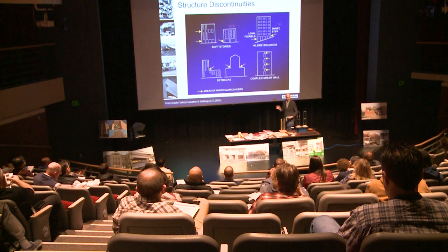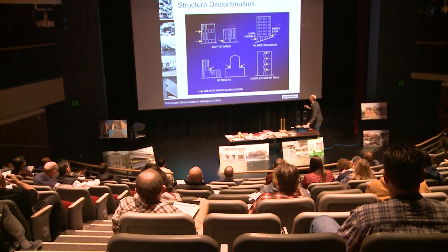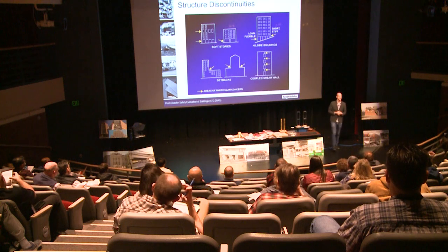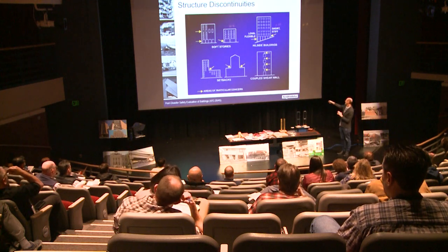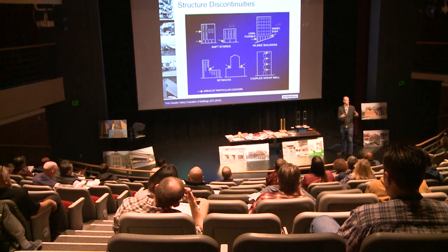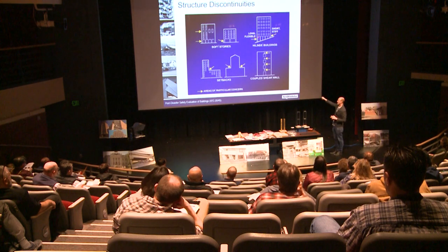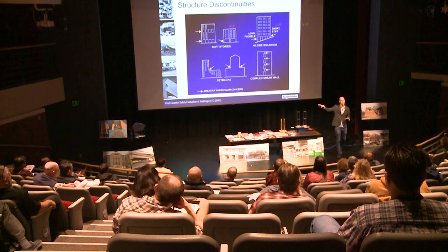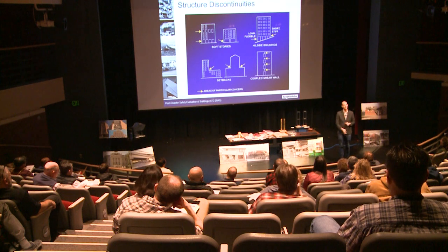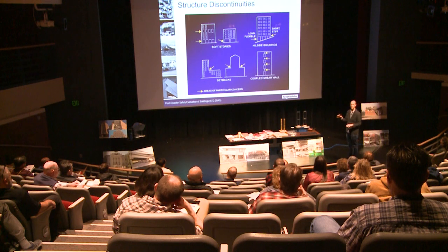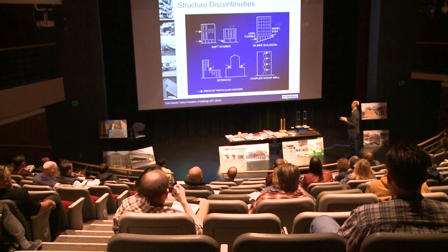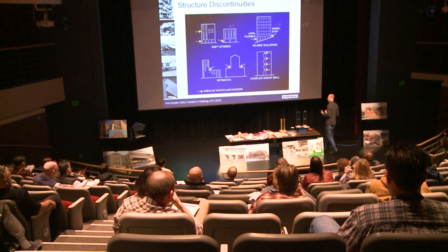Another concept that I just want to take a second to deviate and talk about for this hillside building is, let's say all the columns on this building are equal, the same columns. So they're the equal cross-section, same reinforcement, same everything. We have shorter, stiffer ones, and then longer, flexible ones. You remember, say the columns are 2 times taller on the downhill side. From a lateral standpoint, do you remember how much stiffer the stiffer ones are? That's 2 times 2 times 2. So these stiff ones are 8 times stiffer.